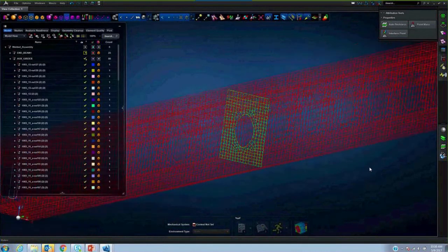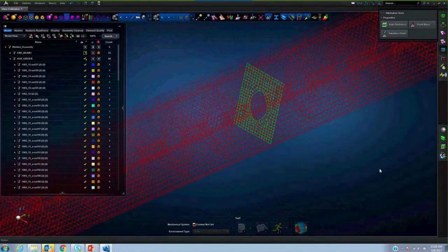if you notice here, that's the inside baffle wall that we created a mesh. Now, how can I connect this part to the rest of the parts? We have two techniques in Apex today, in addition to many other connections one can create. For a large welded structure, either you can create the glue or you can tie connection. Let's try both of them in these examples.